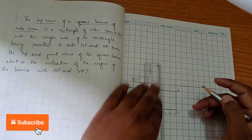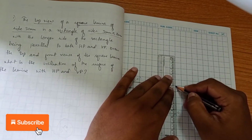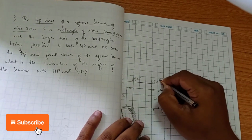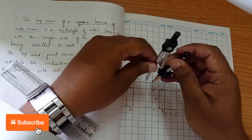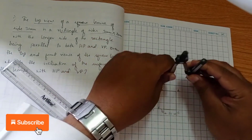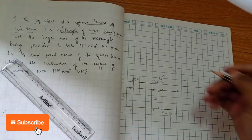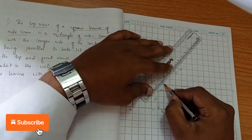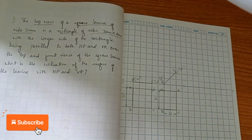Now we have to find out the angle of inclination. How to do it? Just project the lines upward here. Take a reference of this B dash and C dash. By measuring this length from B dash to C dash, we are going to cut the arc. So this is C dash and D dash. Now we have to join this after cutting the arc. Then we will find out how much the angle of inclination is.